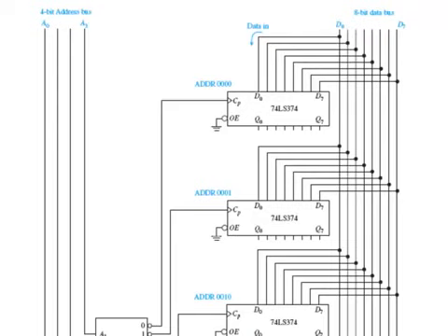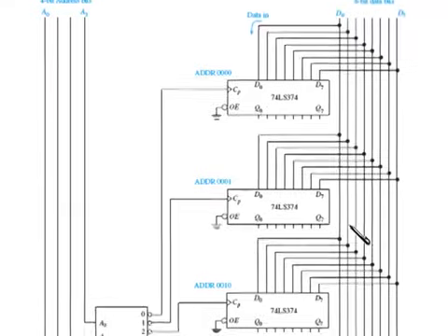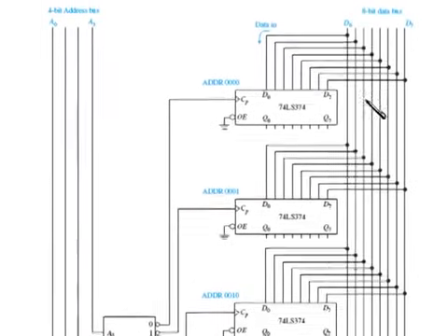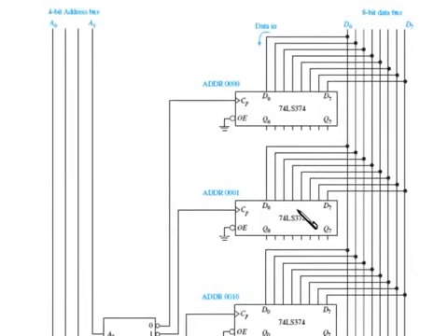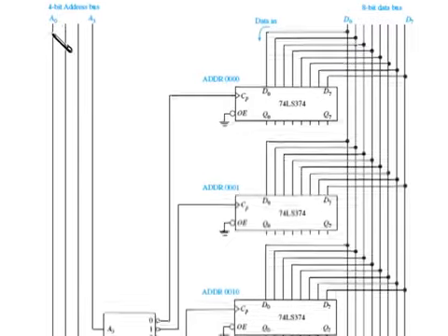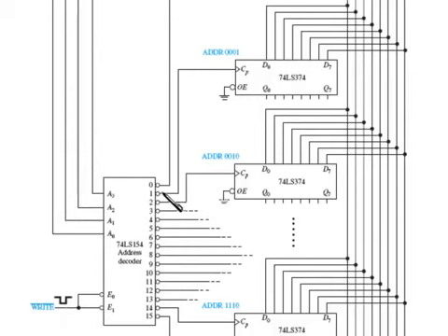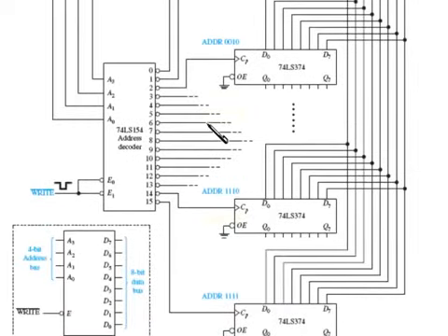second register. So you change this data, and this data, by the way, travels down a data bus. They all get to see it, but only the one you select is the one that's going to receive it. So here's the new data for this register. It's sitting down here. We're going to set up 0001, pulse the write line. The number 1 line goes low to high. That's going to trigger this clock, so the data that's on the data bus is going to go into the second 8-bit register, and so on all the way down for all 16 registers.